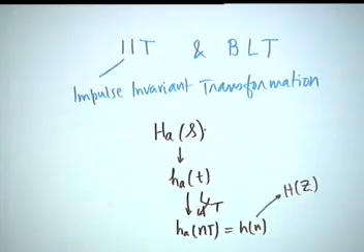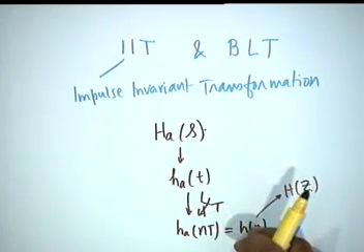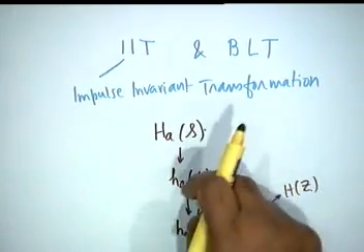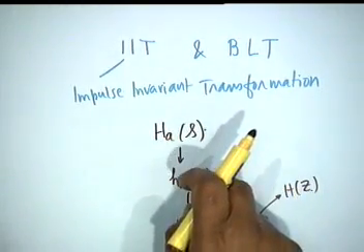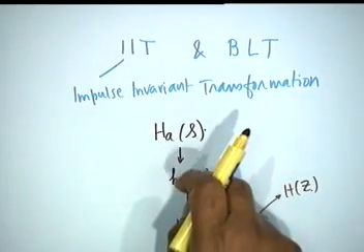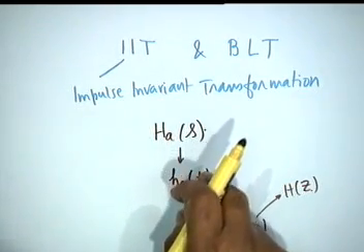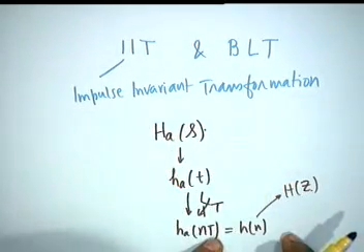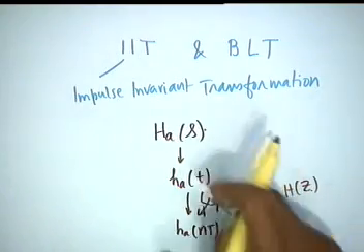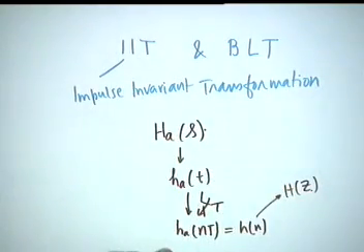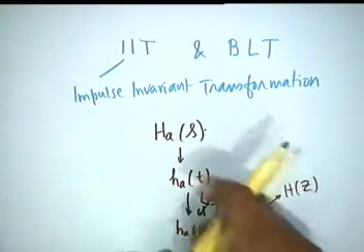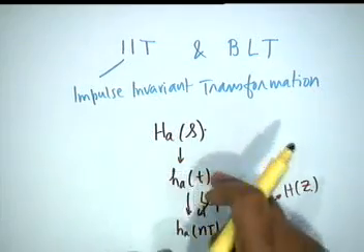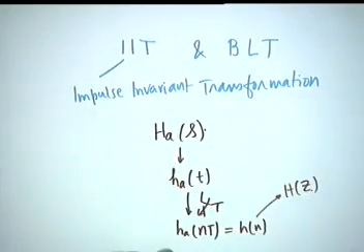That is, the digital filter impulse response is the sampled version of the analog filter impulse response, and if the sampling theorem has been respected in the process, then there should be a one-to-one representation. That is, given h of n, you should be able to construct h A, and given h A, you should of course obtain h of n. This is the problem.